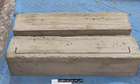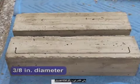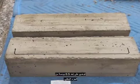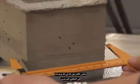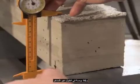Construct two concrete beams, one without reinforcement and one reinforced with two number 3 bars located about 0.5 inches from the bottom. The bars have hooks at the ends to prevent a bar pull-out failure. Both beams are 4-inch by 4-inch in cross-section, with 16 inches in unsupported length.